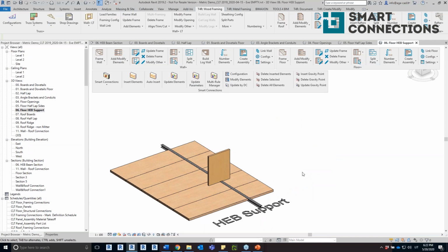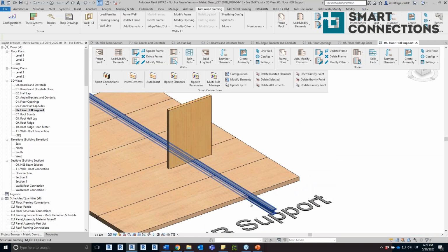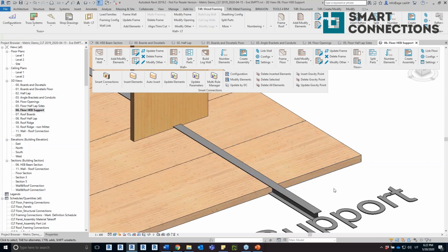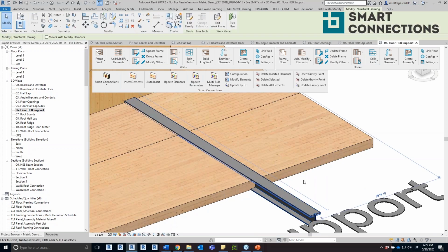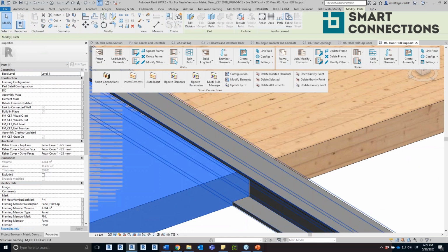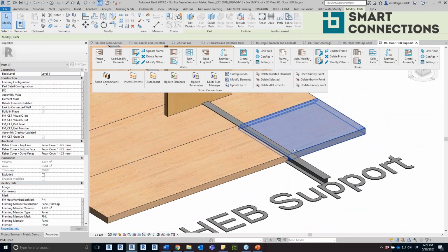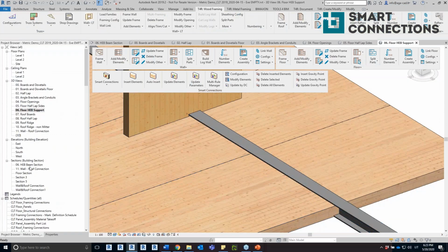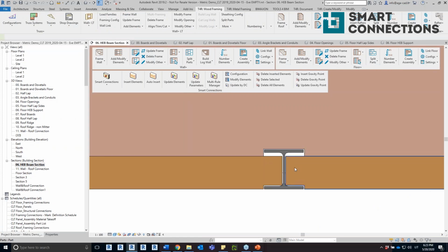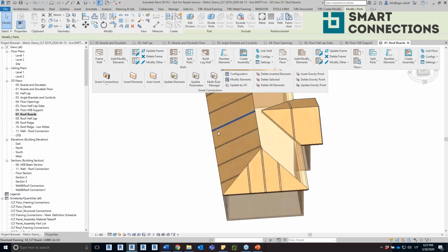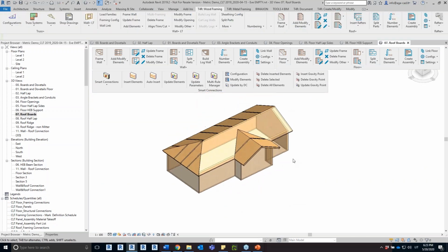Okay, and now another situation where the floor is already split, but I want to show you that we can also use external elements that are in our model, like for example beams, to cut the panels automatically. And also the cut can be added with a certain tolerance. Right now the cut is added with the smart connections. Yeah, so you can see that it's a cut connection, and it creates these special cuts for the CLT floor panels, and it even cuts out the floor part. I can also turn on a section view, so you can see here that everything is created automatically with the software.